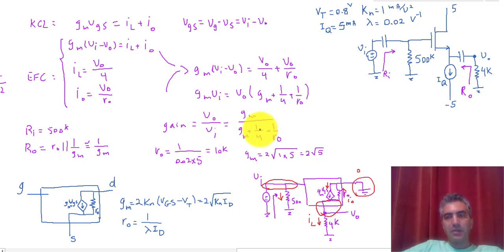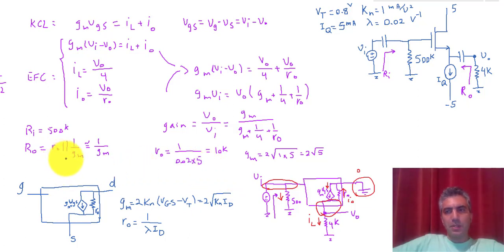Now, when we discussed characteristics of an amplifier, we mentioned that there are 3 important characteristics. For a good voltage amplifier, you look for a very high gain, but also there is input resistance and output resistance. And a good voltage amplifier has to have a really large input resistance and very small output resistance. If you look at the input resistance and output resistance in this question, you can clearly see that the input resistance is very large and the output resistance is a small number. By the way, this is in kilo ohm, because all the currents were in milliamp, so 1/gm would be in kilo ohm. All the resistors are in kilo ohm. So when you put this number here, it is going to be in the range of 220-ish ohm.